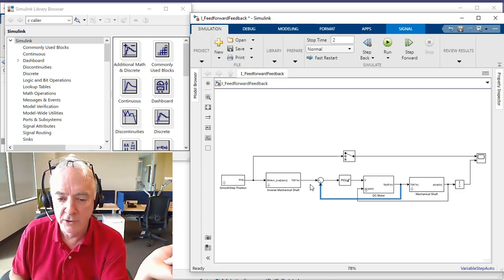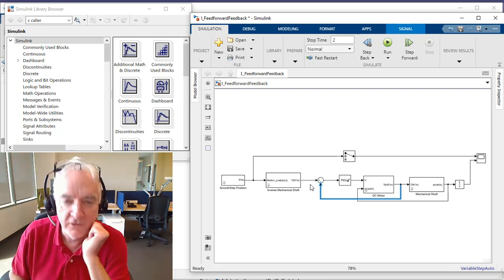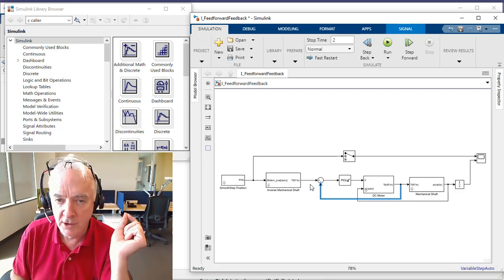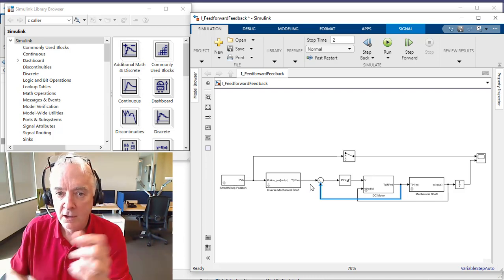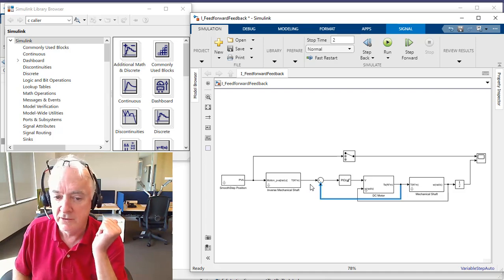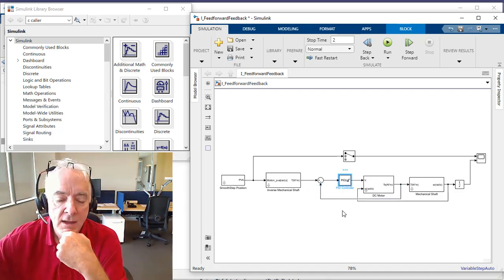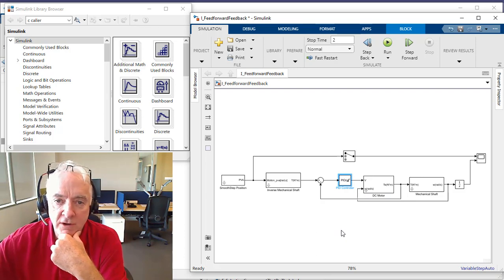And quite often you'll hear people talk about designing current loops. They're talking about feedback control on getting the current that you desire by adjusting voltage, and that's precisely what we're doing. And there's our PID controller that's doing it. You also hear terminology like inner loop, outer loop, and typically the inner loop is that current loop.